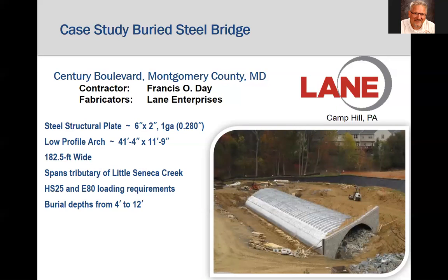Now we're going to look at one of those structural plate buried steel bridges. The Montgomery County Department of Transportation began construction of an extension of Century Boulevard in Germantown, Maryland. The extension crosses a tributary of Little Seneca Creek. The structure is a 41-foot, 4-inch span, low-profile steel structural plate buried steel bridge with an 11-foot, 9-inch vertical clearance.